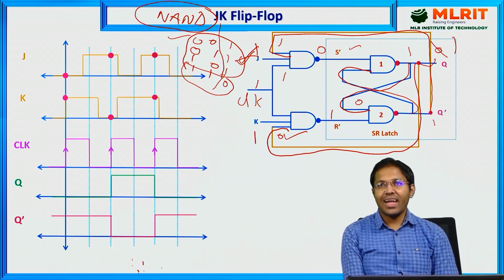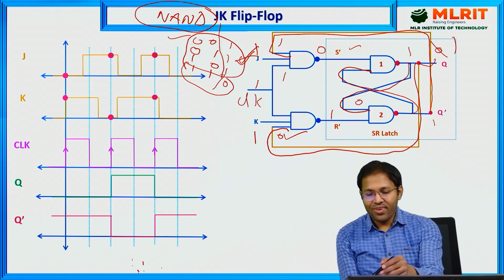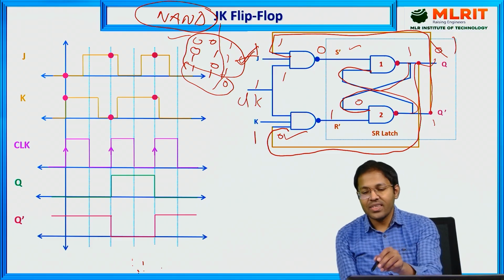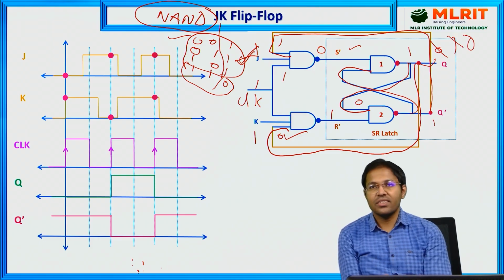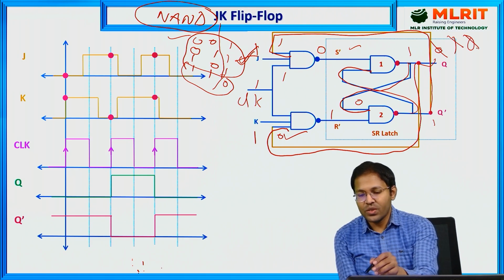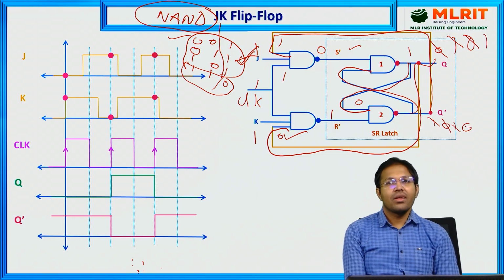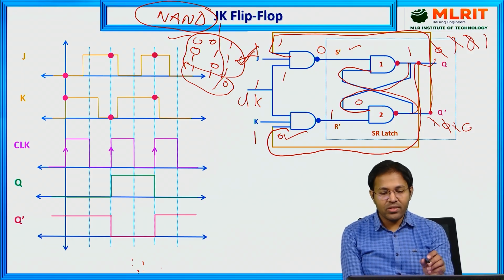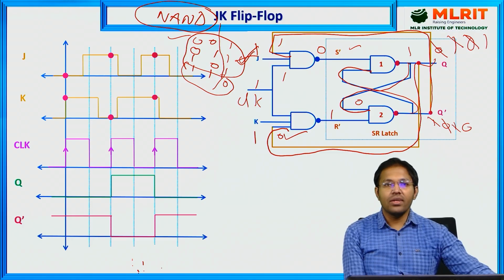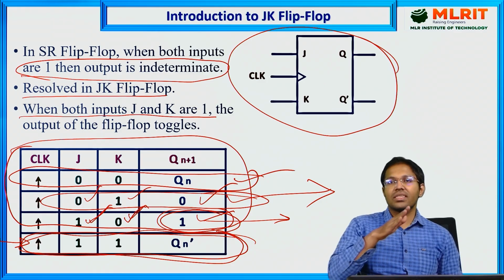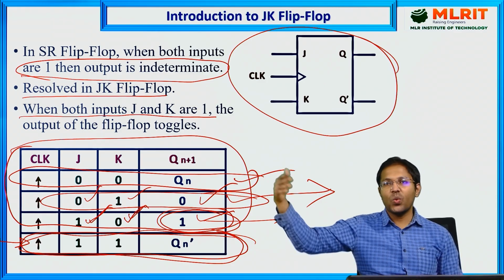One can further analyze that this 1 is again propagating in different places. And now, after analyzing, what you will find is that again this will change to 0, and again it will change to 1, and so on. Likewise here, this will change to 0, this will change to 1, this will change to 0. So, based on that analysis, when both the inputs are 1, the output simply toggles, 0 to 1, 0, 1, and so on.